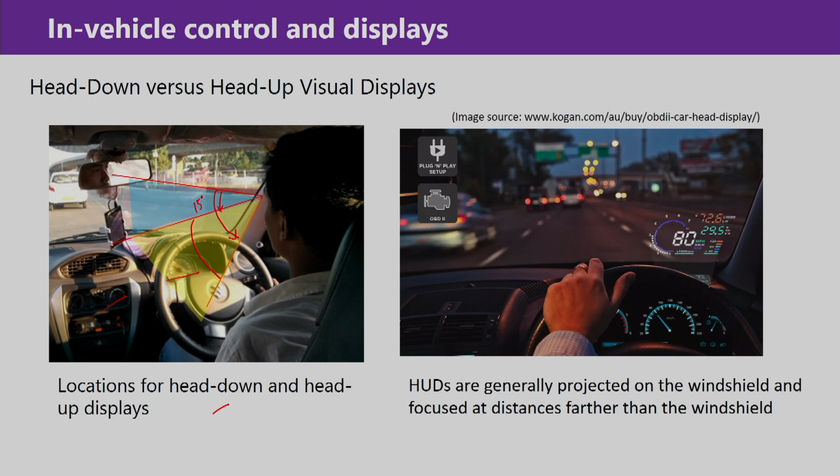While drivers are looking toward these displays, eye movement is required, and if the line of sight movement is more than 20 degrees, then not only eye movement, there is also complementary head movement. So, using both eye movement as well as head movement, drivers visualize all these displays located on the dashboard or at the central instrument panel, viewing through the steering wheel. On the other hand, if we talk about the head up display, head up displays are generally positioned from the straight ahead line of sight 15 degrees down or at the most 5 degrees upward.